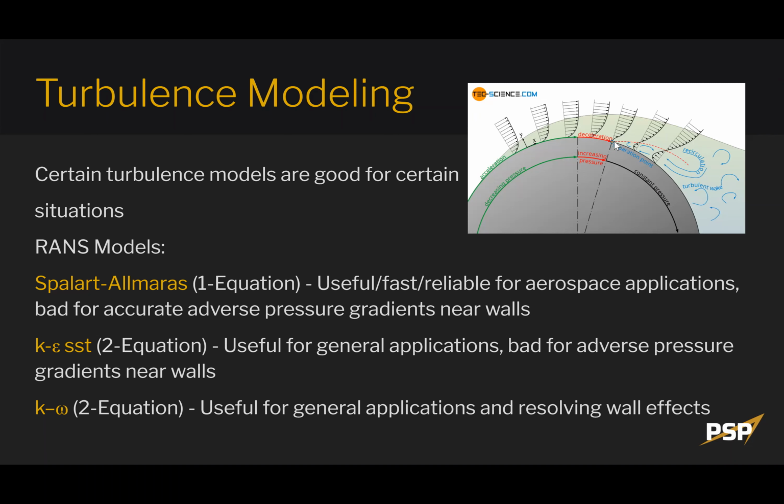You want flow separation to happen later, farther back on your object, and that will decrease the amount of drag. If flow separation is farther up, you'll have more drag; farther back, less drag. That's why golf balls have dimples. Those dimples help to push this separation point farther back, decreasing the amount of drag golf balls have. Spalart-Allmaras is bad at describing where this occurs, so don't use it if you're trying to find that.